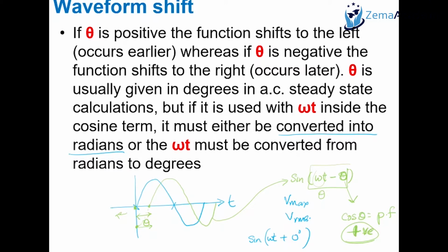Usually, lagging power factor is indicated as a positive value when doing calculations. A leading power factor, because you can say leading, but when you do the calculations, how does the computer or somebody understand from your calculation whether that's lagging or leading? That's where you use positive or negative. But that positive or negative is opposite to this angle, which is where you shouldn't get confused.